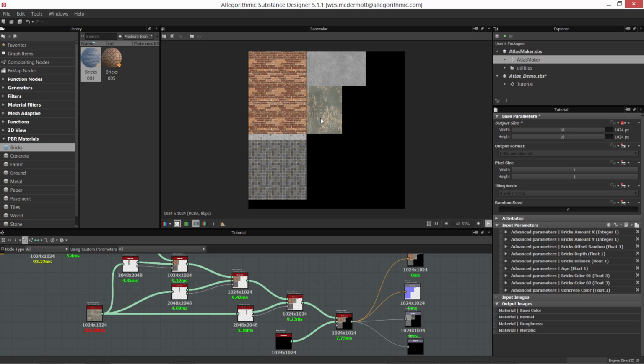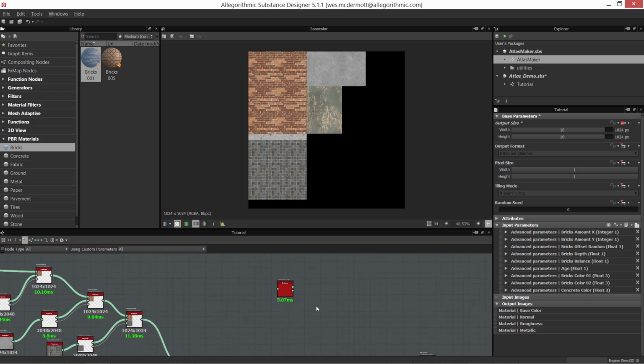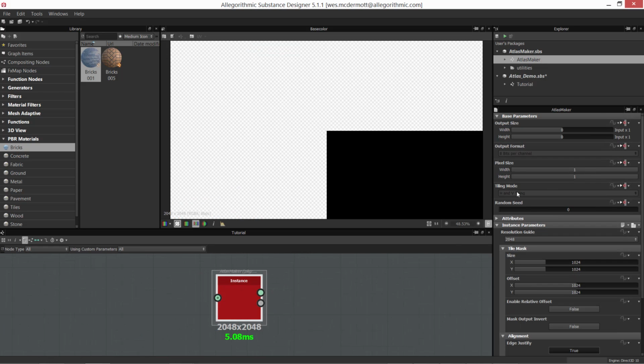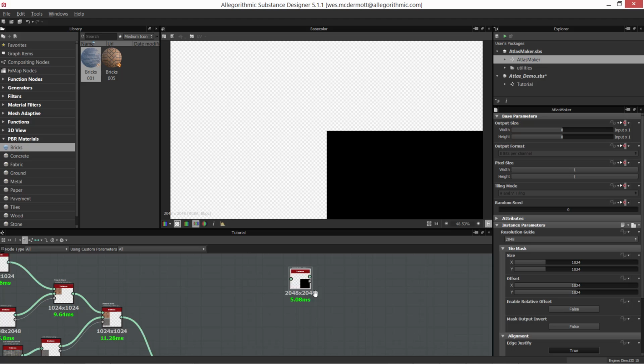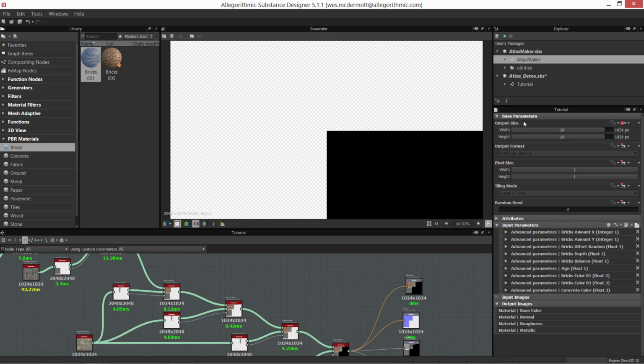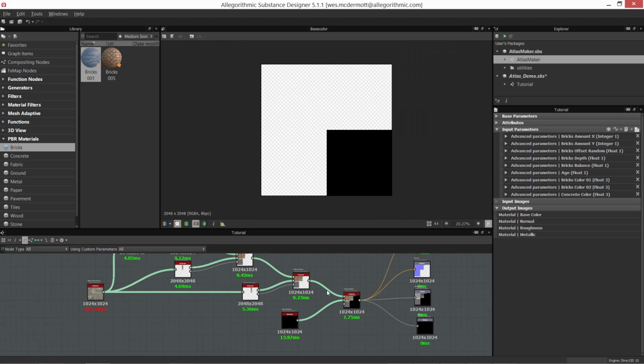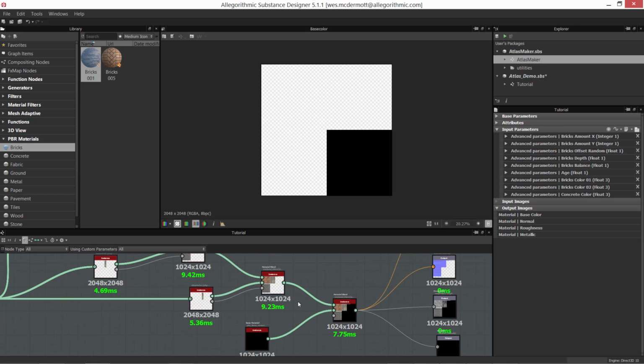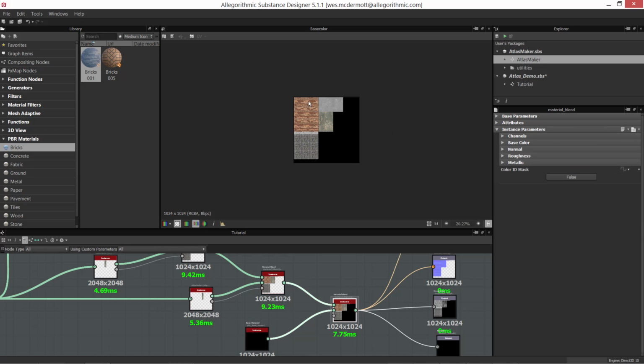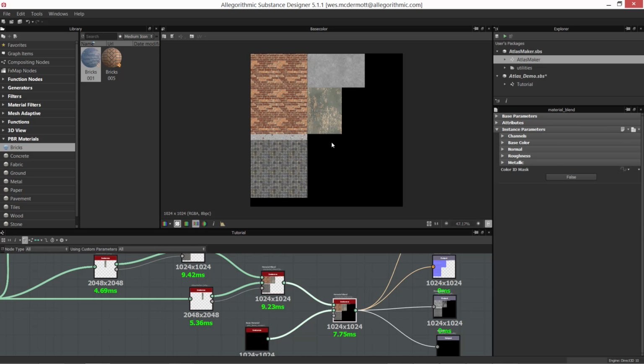And that is because the actual offset values that we place are driven off this resolution guide, but the actual resizing of the atlas itself is based on the graph. Now, another thing you have to be careful about is to think in terms of your max resolution. Like I said before, this graph was at 2048, but let's say this final texture atlas I'm creating, the max it's ever going to be is 1K, and that's what it's going to be.